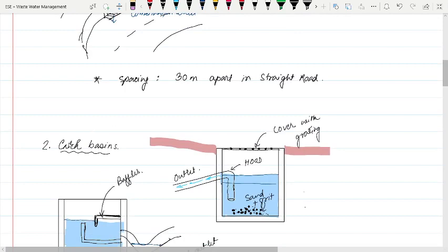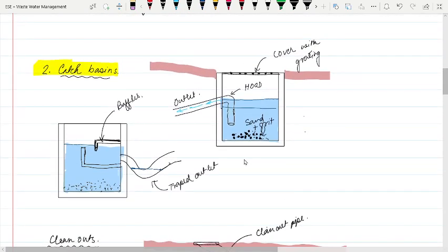Next comes the catch basin. Inlets will lead you to catch basins. Catch basins generally catch the particulates that flow inside the sewer with stormwater. If we let most of the solid particles go through the sewer pipes, our treatment facility will be much harder. So that is why we want those particles to stay in those basins.